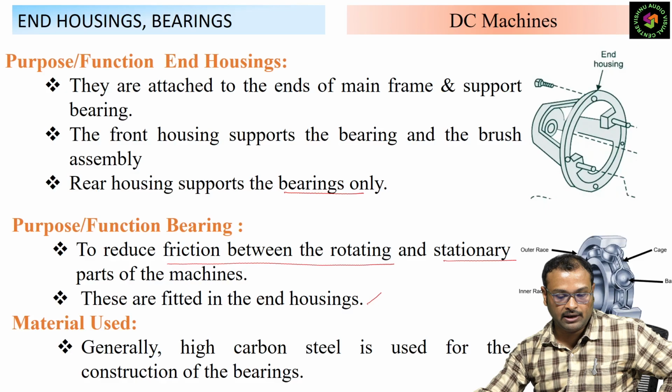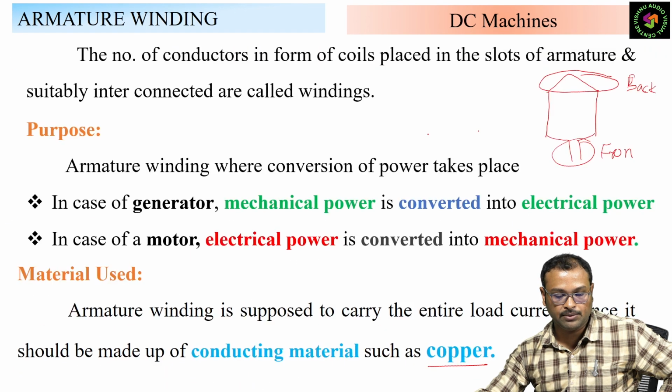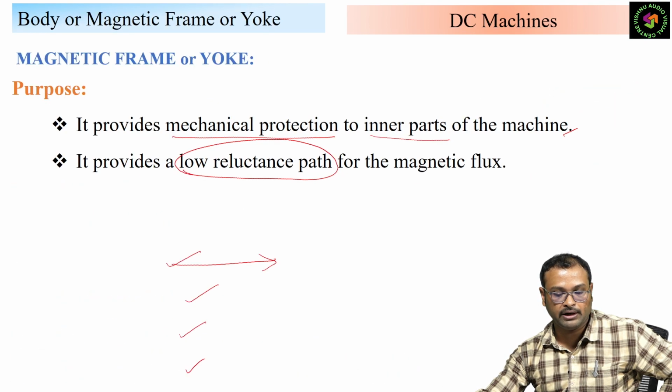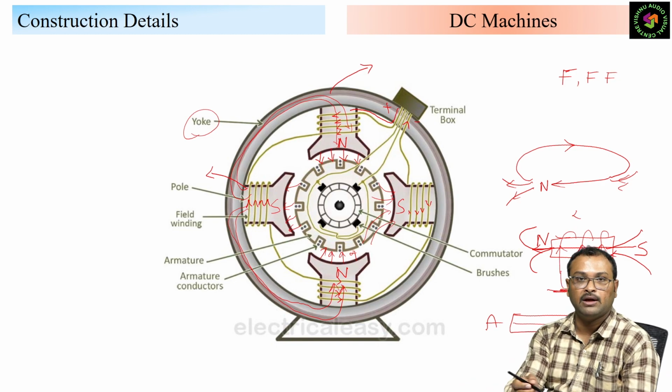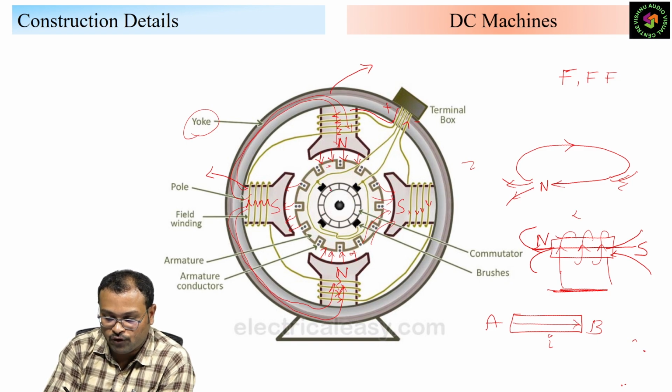And as we said, in the exam you have to draw the circuit diagram and explain each and every term, what is the purpose of it, what it is made up of. Here, one more time, this diagram. This is the armature core, these are the armature slots, and in between the armature conductors are available. Whatever wire comes from these conductors goes to the brushes. Here 4 poles are there and 4 brushes are available. So 4 brushes means which winding? Definitely it is a lap winding.